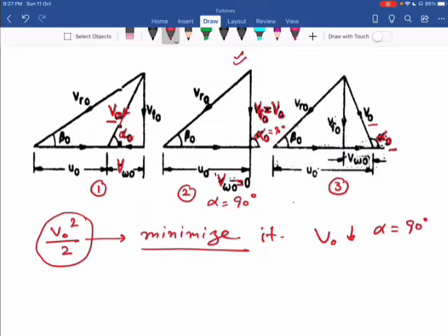Now further in this velocity triangle, you can see VWO, the whirl component of velocity, is 0. Thus in practice, all the reaction turbines are usually designed for this radial flow. That means the angle alpha O is equal to 90 degree. So for the outlet, we have this velocity triangle.